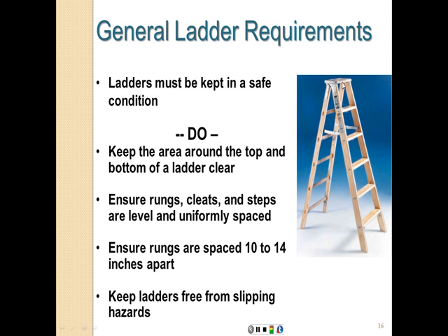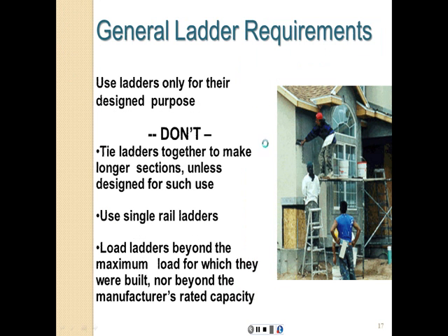If you're going to use any slippery material, make sure that if you have any drops falling on these steps, you clean them before using the ladder. Use ladders only for their designed purpose. Unfortunately, people misuse these ladders. They are designed primarily to move from one level to another, or to stand on that ladder, if it's properly supported, to do certain types of jobs. But misusing these ladders usually leads to the collapse of that platform and to some severe injuries.